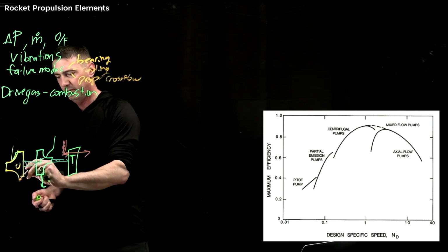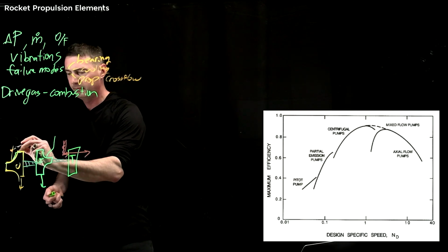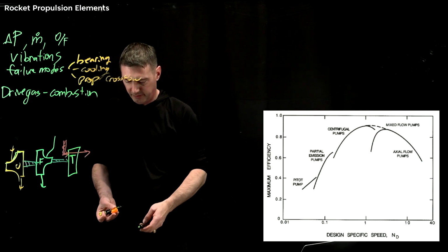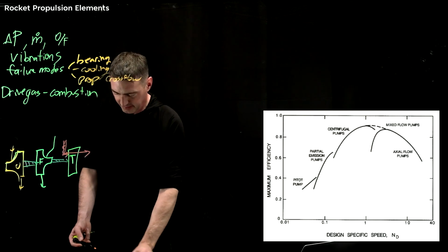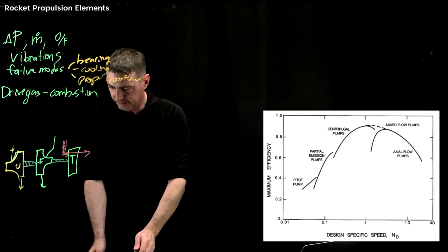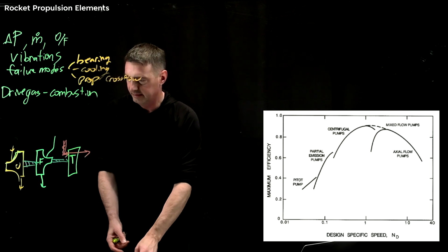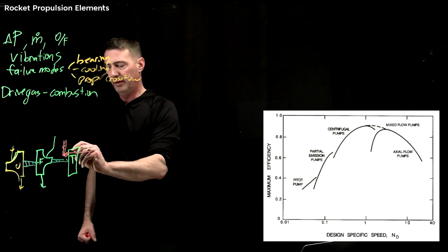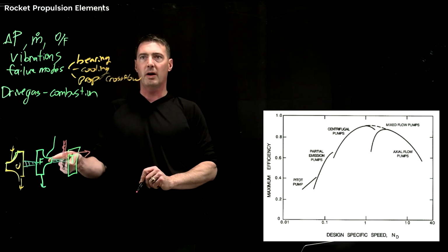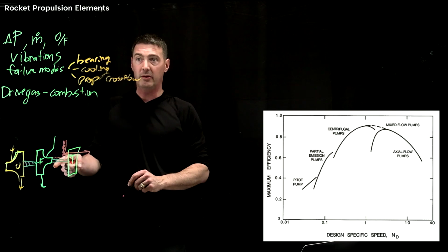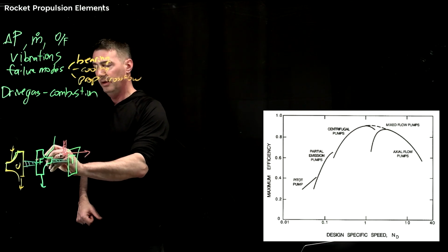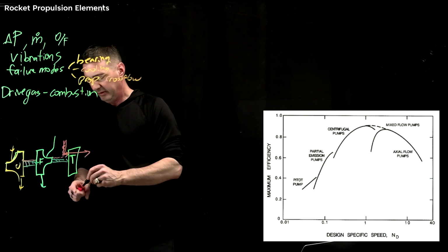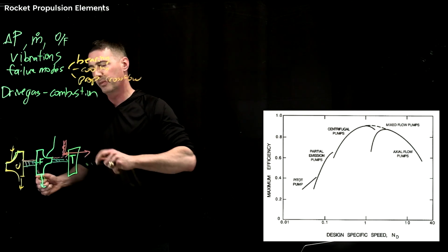All right. One of the things that can happen in that failure mode is if some of these hot gases kind of make their way back. So that's one bad part. There's a failure mode here where these hot gases walk back. Now you've lost some of your cooling. This is getting too hot. But you also have a failure mode here. Usually this common shaft has what's called your interpropellant seal, or IPS.